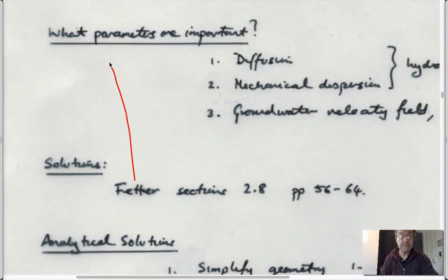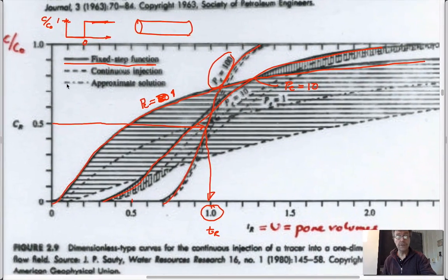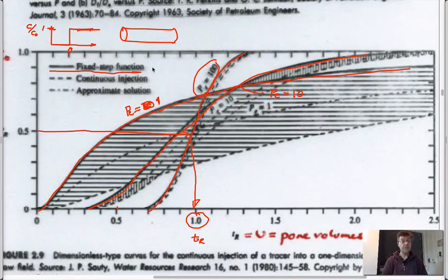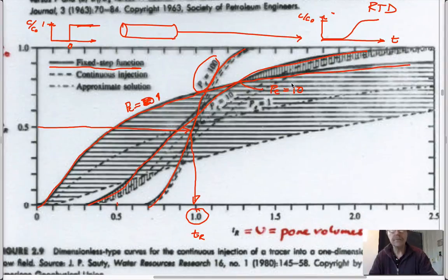But basically all they're doing is allowing us to represent the behaviors if you wanted to define what the concentration distributions were downstream. And so if you wanted to put together the concentration arrival map, the so-called residence time distribution, the RTD curve, versus time and concentration, then you have exactly that here. That's exactly what this is. And where it comes from is just this calculation from these somewhat complicated functions, but not very difficult to calculate if you have something like a scientific calculator or MATLAB or whatever.